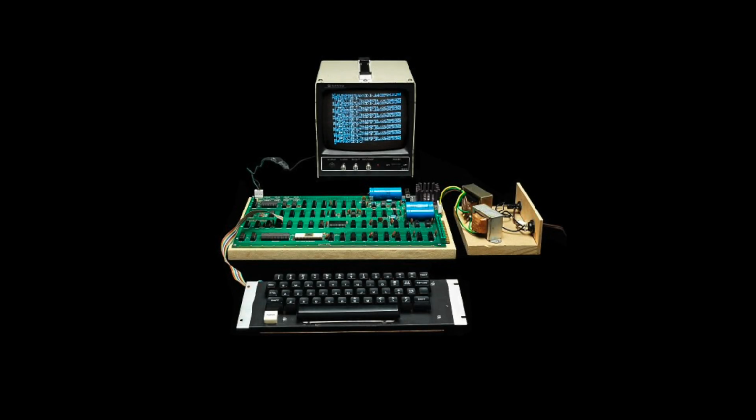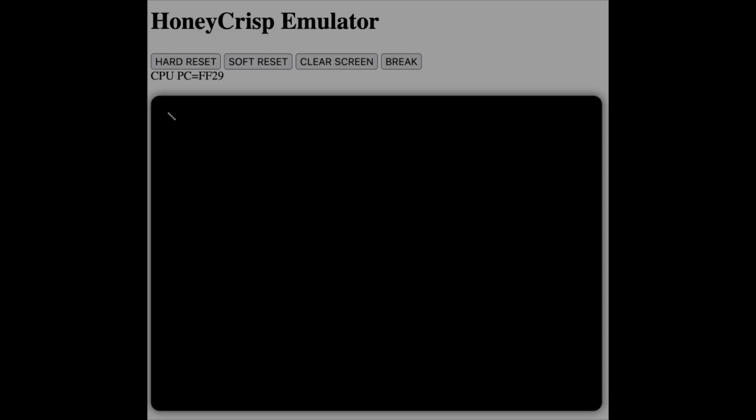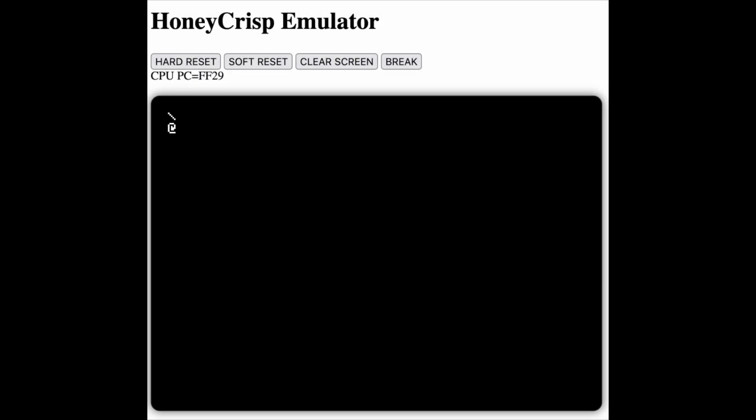the Apple-1. So, this lower-end variant of the 2513 only included some of the symbol glyphs and only included the uppercase alpha glyphs, right? And on the internet today, most TrueType font recreations of the 2513 character ROM include all of these glyphs from the high-end version. There are no glyphs from the lower-end variant of the 2513. Or should I say, there are no font recreations of just the glyphs from the 2513 lower-end variation. That said, I've had to patch the higher-end 2513 font to essentially only have the glyphs that were supported by the lower-end variation of the same chip.